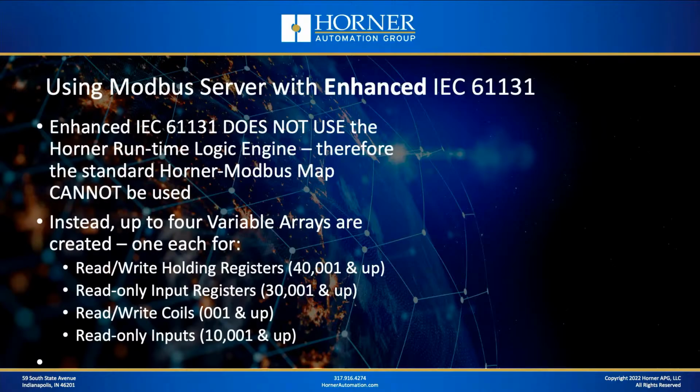Now, we don't have to support all 4 types. We might only support just one, and in that scenario, we only have to create one of those arrays. However, if we want to create all 4, we create 4 arrays. And the arrays don't have to be 10,000 integers long or 10,000 bits long or anything like that. If we've only got 4 holding registers we want to share, we can make the array 4 words long.